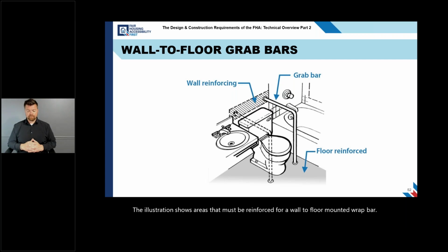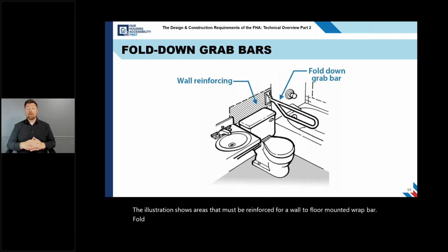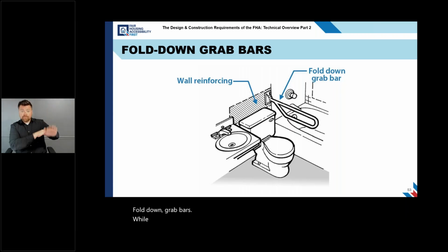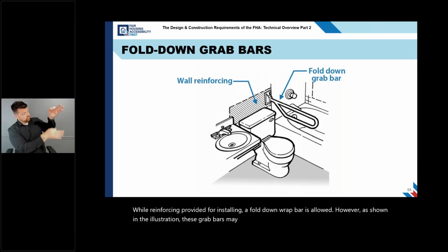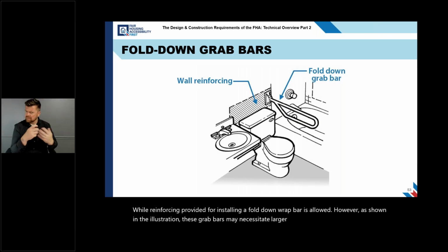Fold down grab bars. Wall reinforcing provided for installing a fold down grab bar is allowed. However, as shown in the illustration, these grab bars may necessitate larger reinforcing areas than conventional wall-mounted bars.